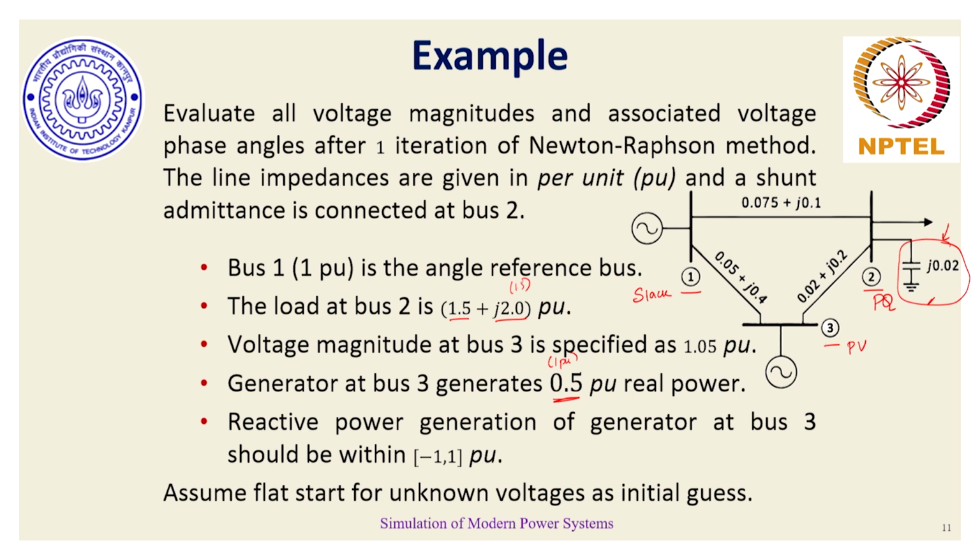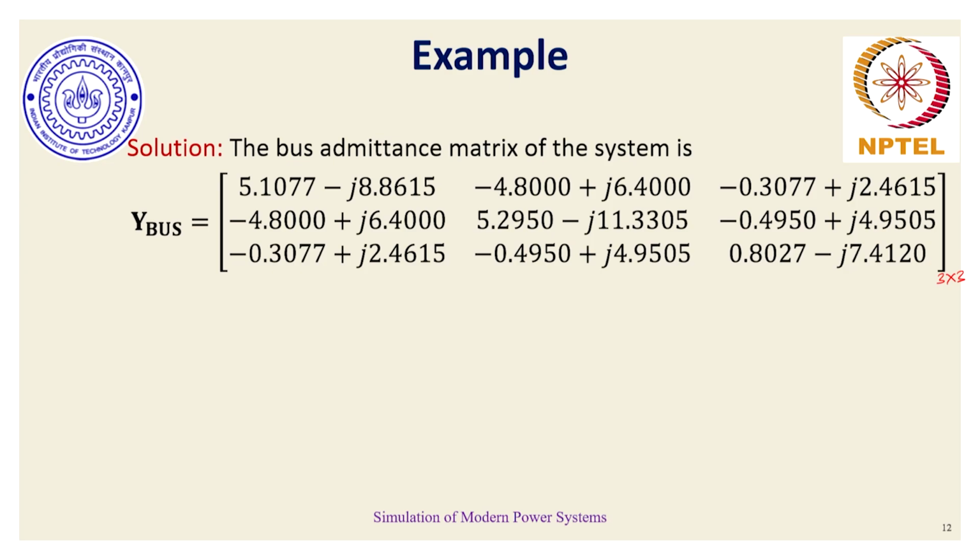or unique bus injection currents. Despite that discussion, in the previous example in the Newton-Raphson polar version, we had a singular Y-bus and we were able to get the converged voltage phasors of all buses. We were able to find the currents. Now, the question that remains here is how? If Y-bus is singular, how did power flow analysis give a voltage solution in the first place?